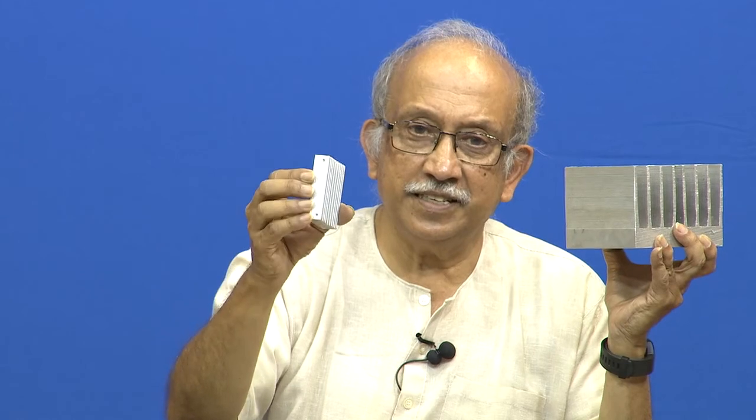And now you would have guessed what it is. The main thing it does is to increase the area of interaction with the ambient. You will have them in all these things, to increase the effective surface area. One way is to try to calculate all these areas. Another is if you take a simple device like this and try it out, directly you can get the heat transfer coefficient in convection with the given rates, and then if you just take the area, you will be able to get it.